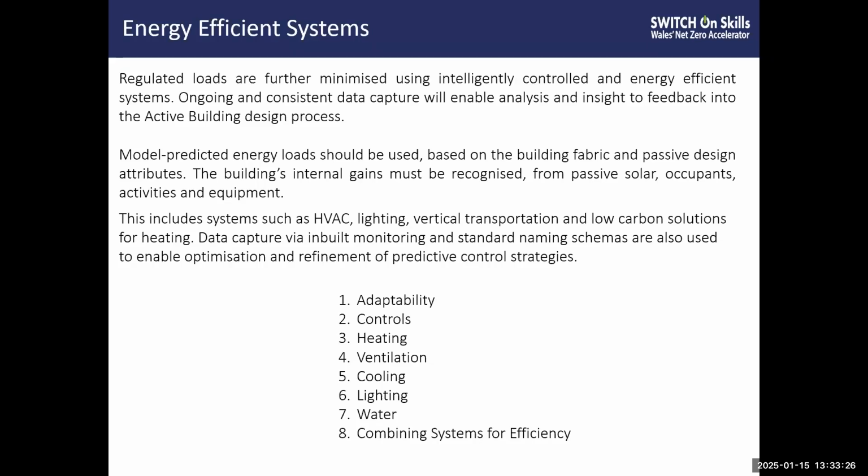Ongoing data capture then will enable analysis and insight into a feedback loop into the active building design process. We can predict energy loads using models and then base this on the building fabric and passive design attributes. And then the building's internal gains must be recognized from solar, occupants, activities, and equipment. And all this can feed back into the system.